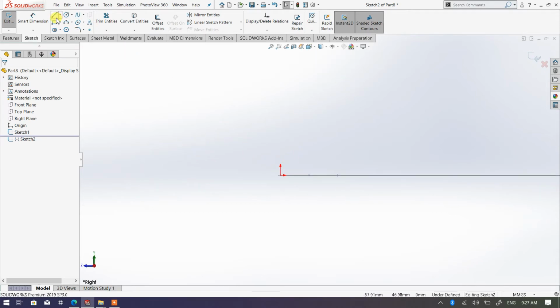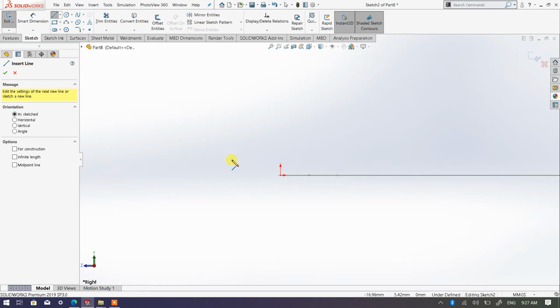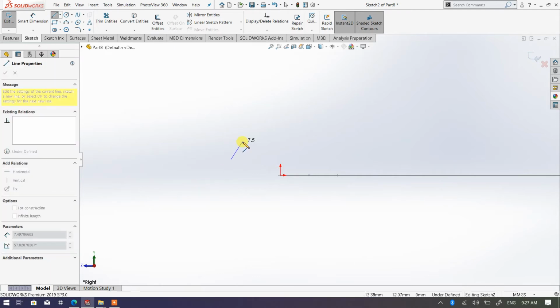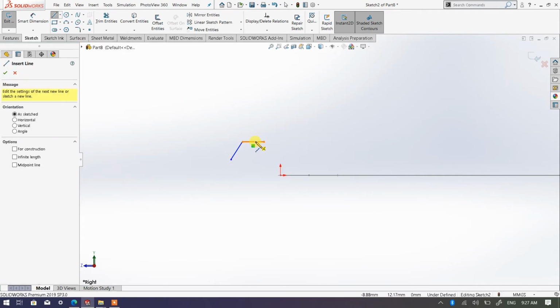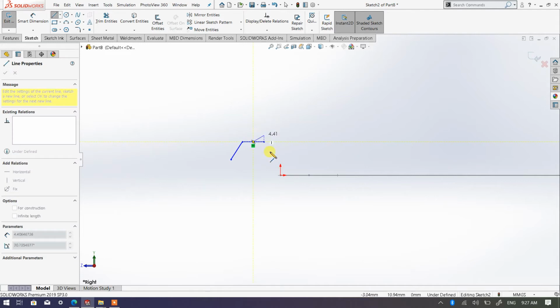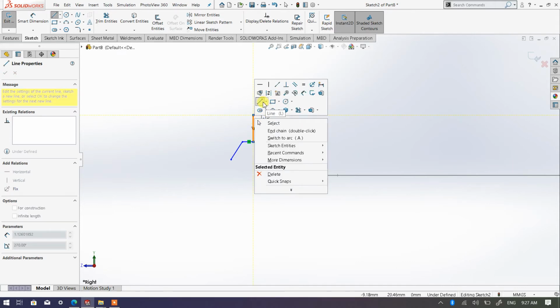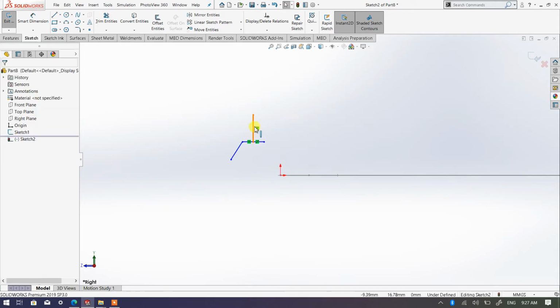Let's say, for example, I just simply create a simple sketch. You can have it like that over here. You can indicate dimensions if you want to. However, this one I just simply sketch like this without any dimensions. So I'm going to create a line here, which represents the guideline, because I'm going to mirror this line over here from here to here.